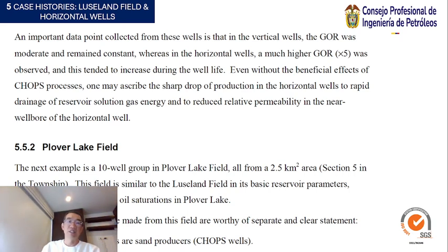And this tended to increase during the well life, even without the beneficial effects of CHOPS processes. One may ascribe the sharp drop of production in the horizontal wells to rapid drainage of reservoir solution gas energy and to reduced relative permeability in the near wellbore of the horizontal well.